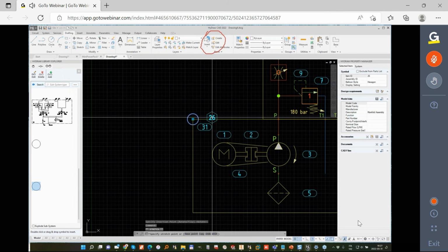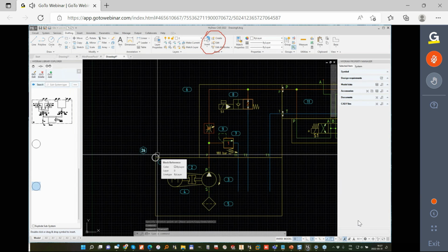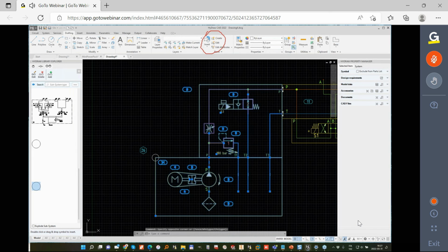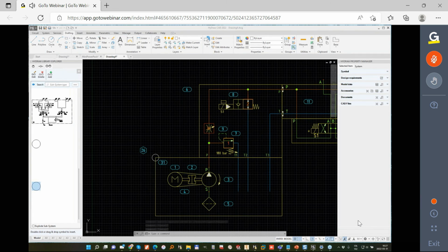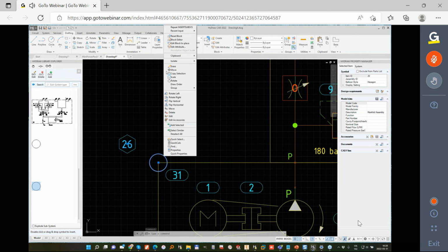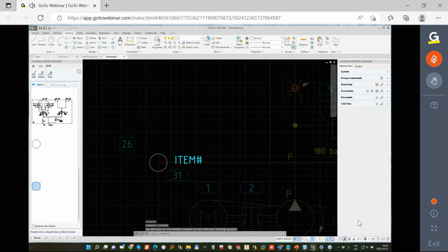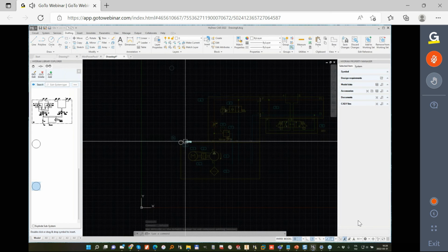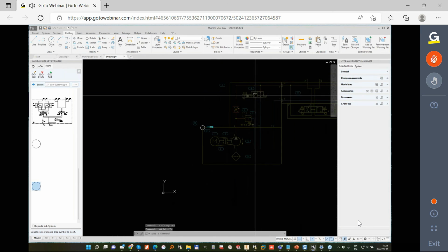And now, as you can see, I have my item number 26. So now what I want to do is bring inside my subsystem all these entities. There is an AutoCAD function called edit block in place. So we can touch the subsystem, the new block that we have created, right click and edit block in place. Edit block in place is a nice functionality of the AutoCAD engine, because it allows you to work by looking at what is behind. So we have all this symbol.